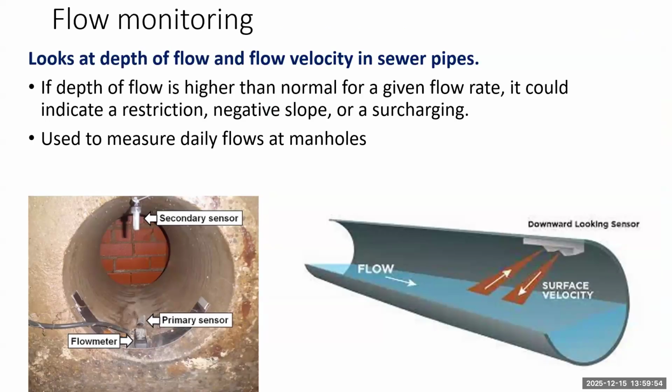And then we have an ultrasonic meter that measures the velocity of flow. And those two things combined are logged and processed. And this type of study can go on for a few weeks, or it can go on for several months, because you want to capture what's going on during dry flows and wet flows, when groundwater levels are high, when groundwater levels are low, and so on.